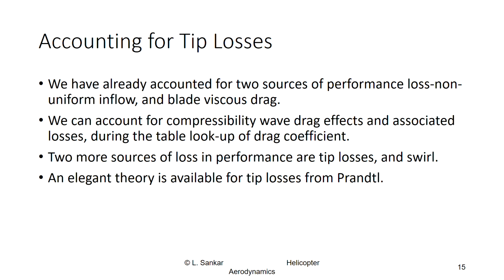So now we look at the tip loss. Remember, right at the blade tip, our actuator disk model and our blade element model say it's still producing a CL of a times alpha. But we know right near the tip, the pressure will equalize between the bottom side and top side, so the lift coefficient should go to 0. So we want to correct the tip region.